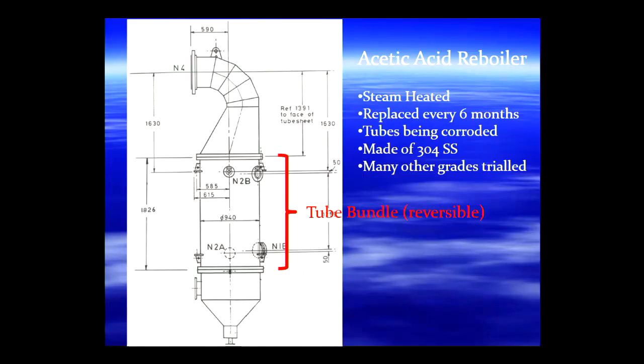And therefore, anything that goes wrong, if something breaks down, a pump or a pipe or a valve or a reactor or a heat exchanger, whatever it might be, and it causes the plant to stop, the clock starts ticking immediately. So if you've got a $5,000 pump that somehow malfunctions, and it takes you 2 days to repair it, you're $500,000 in the red. So the cost of the pump becomes almost irrelevant. So downtime usually swamps any material costs, everything.